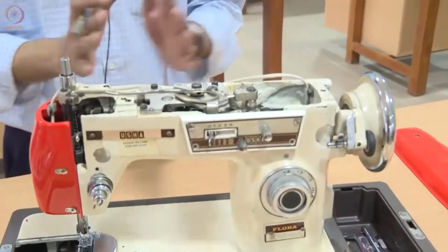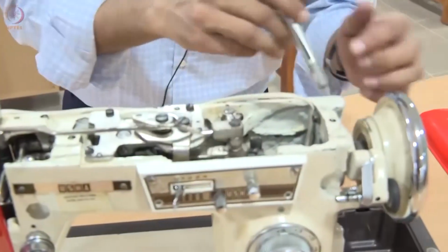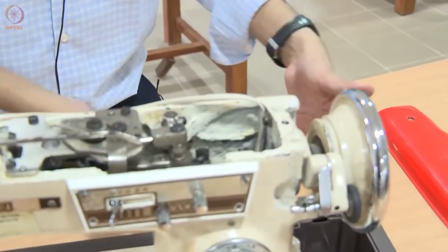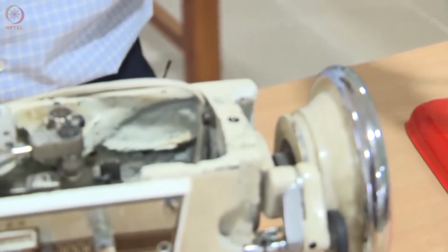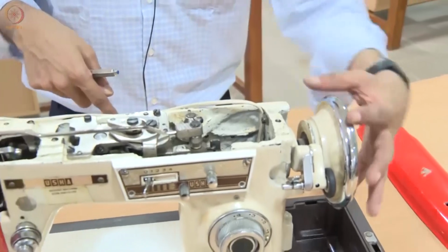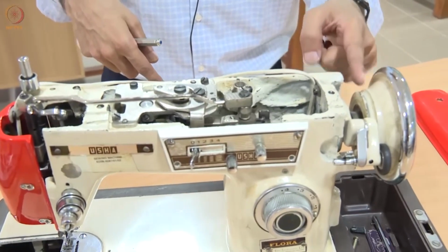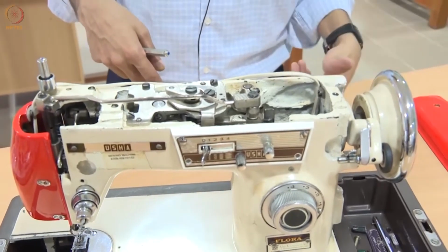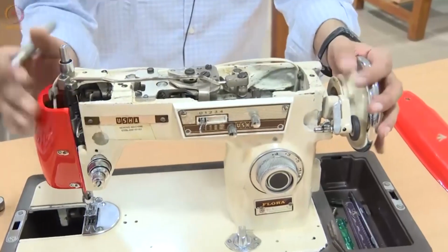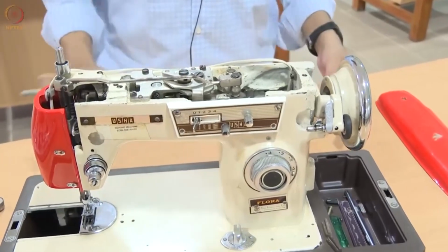This machine is powered by an external motor. You can see there is a groove here. You will typically have a belt running, and this machine will be bolted onto a table, and you have an electric motor that is connected to this hand wheel here. You have a pulley groove here, so a belt powers this machine. The motor is not an integral part of this machine. Since it is 30 years old, the motor is externally placed. Modern machines have them internally as part of the machinery.